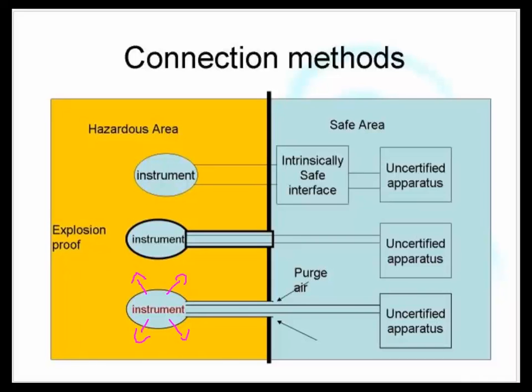With the third method, we have a couple of problems. We have to have a sensor there which is proving airflow. And then we have a sensor just in here which is proving that we have pressure. If either one of those sensors breaks down, we have to power the instrument down. That can make it a quite unreliable instrument, especially with the airflow sensor. It's very hard to detect a small airflow. The pressure sensor is also a pain because that means if you open the door, the whole instrument shuts down.